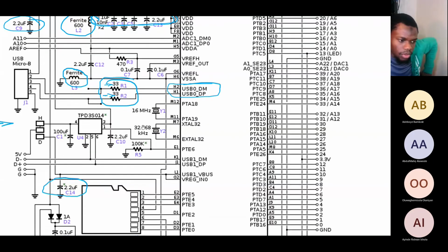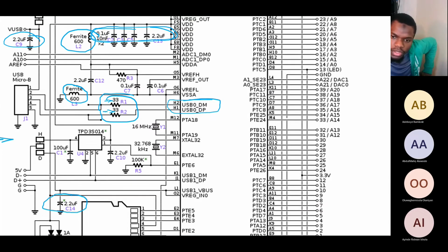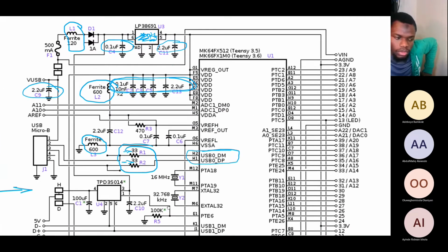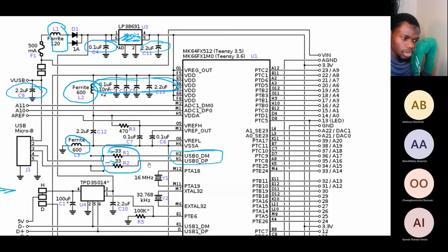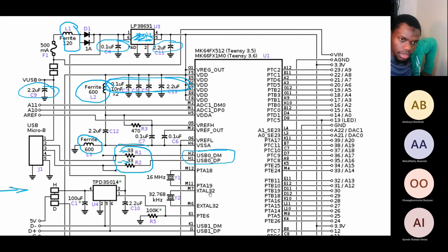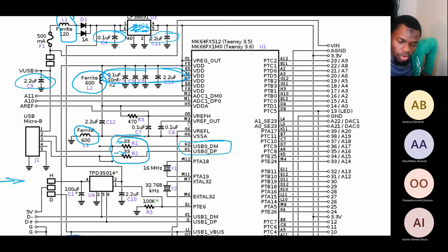So one of the things you look at when you are deciding on picking a microcontroller platform for whatever project you want to do is some of these things I'm mentioning. For example, if you need to communicate with a particular sensor and the sensor uses a particular protocol, you need to make sure that the microcontroller family you are picking can use that protocol.